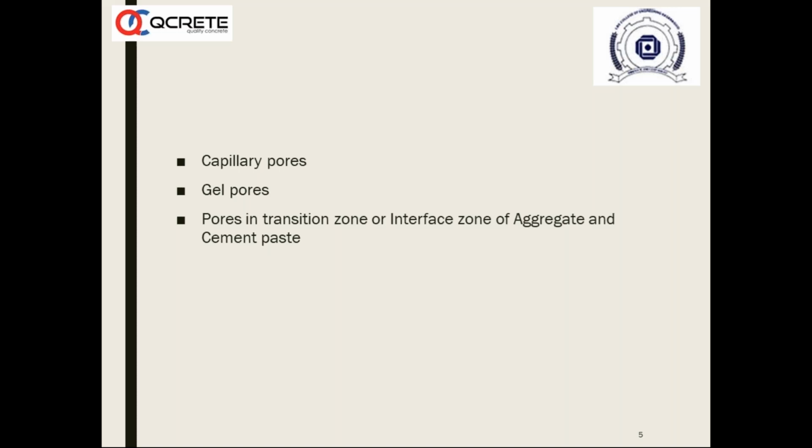When water evaporates, it cannot take a difficult route. It will take the path of least resistance. It cannot pierce a stone or aggregate, and it cannot go out piercing a stone. It takes an easy path. It will take the mortar route, and if this route is at the aggregate transition, a pore formed there interferes with the bond strength actually.